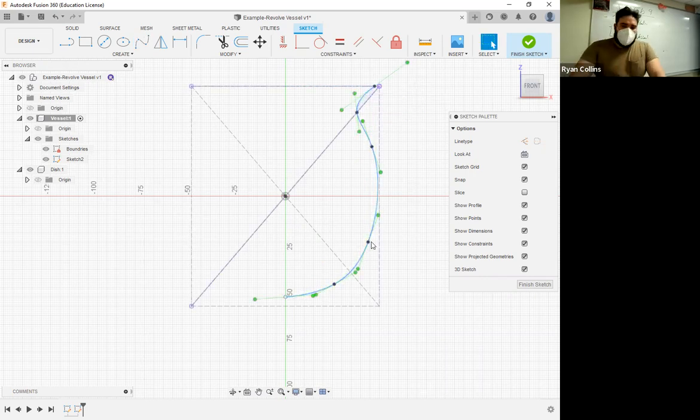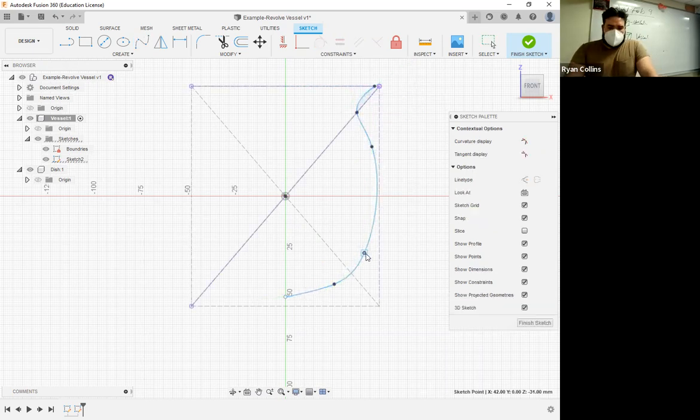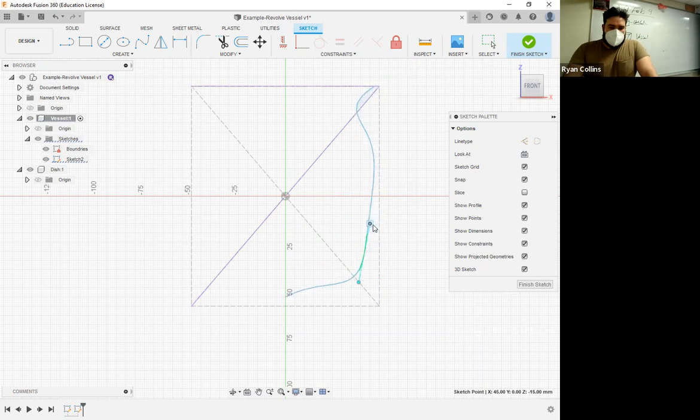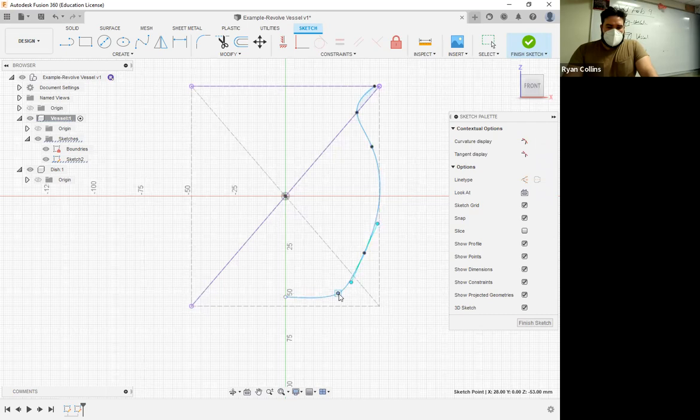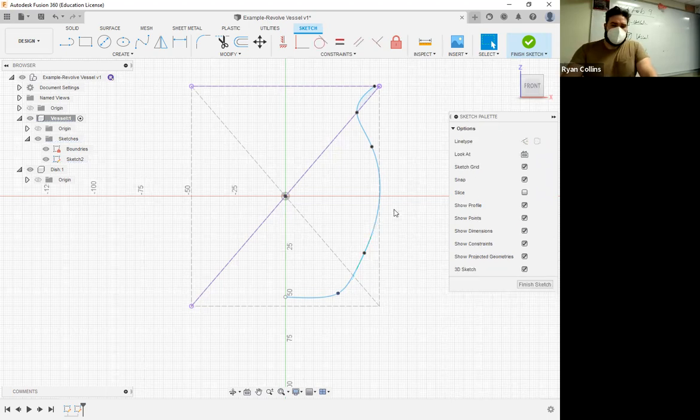Fit point spline. Now I have some points. I can manipulate these points. I can select that and drag out the handlebars, really mess this thing up. I wouldn't go too crazy, but somewhere-ish. That works, something to that effect. Hit enter, escape it, finish the tool, great.